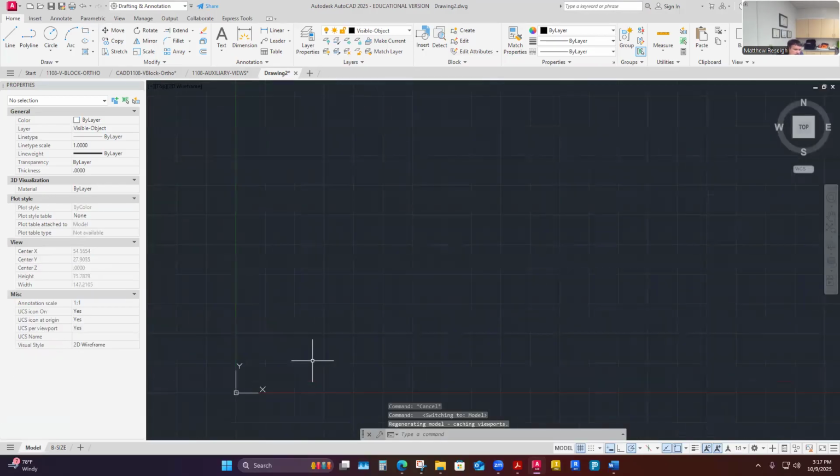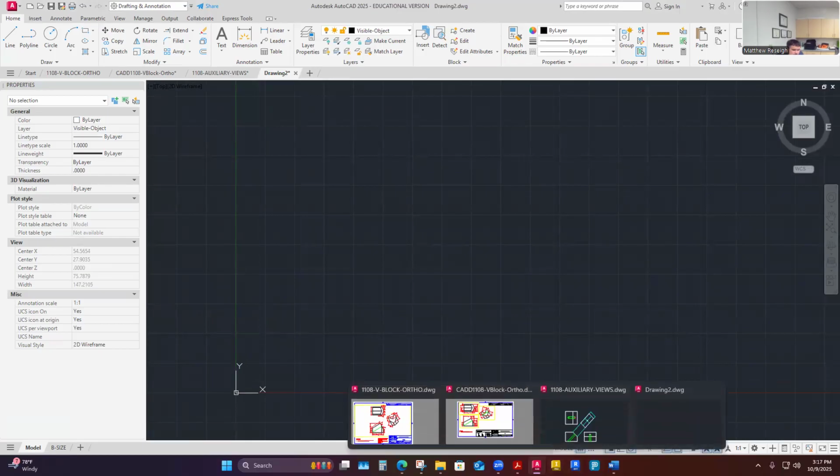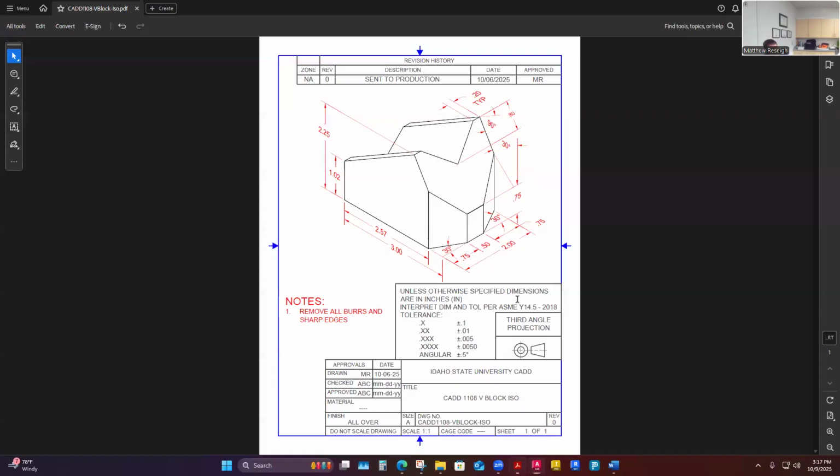So let me just start with the front and top view and talk through what views I might need. I'll talk through my overall dimensions right here. I'm going to make my boundary areas for all three of my views, and then I'll talk through, before I take off running, which views I might start with. Mostly always starting with the front view for me. But I need some boundaries of 3 by 2.25 high, so 3 inches wide by 2.25 high by 2 inches deep. So I'm going to take those at least and develop the boundaries for them here.